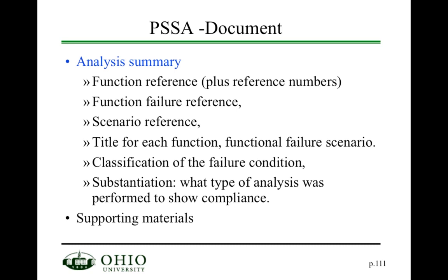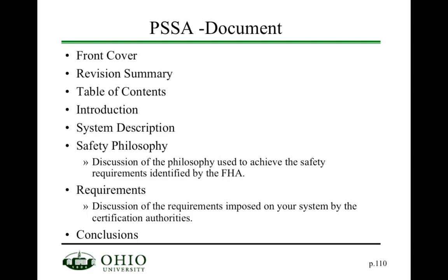So the fault tree analysis, the data dependency diagrams, and the Markov analysis, you can really do both qualitatively, so without the numbers, without the info on the actual failure rates and probabilities, or you can do them quantitatively, so that means with the information about the failure rates. If you do them qualitatively, this is typically part of the PSA, the Preliminary System Safety Assessment, and if you do it quantitatively, this is typically part of the System Safety Assessment.